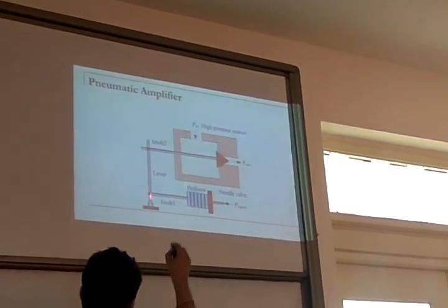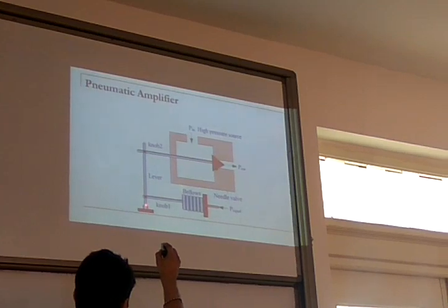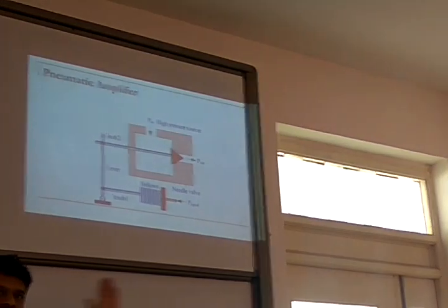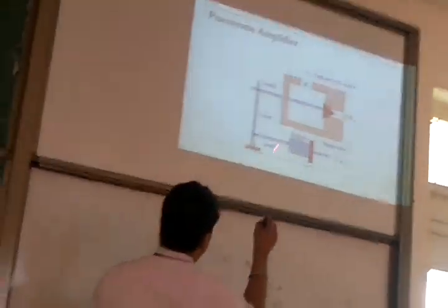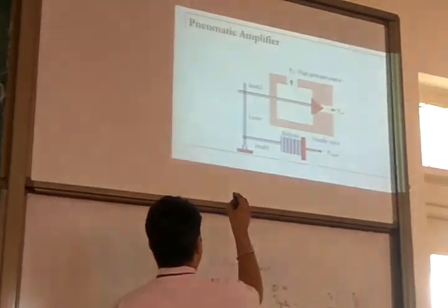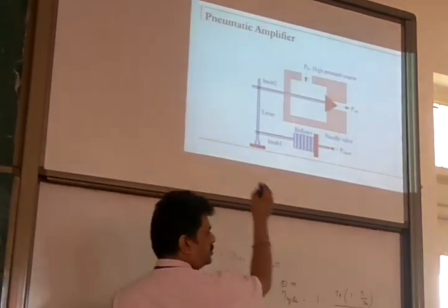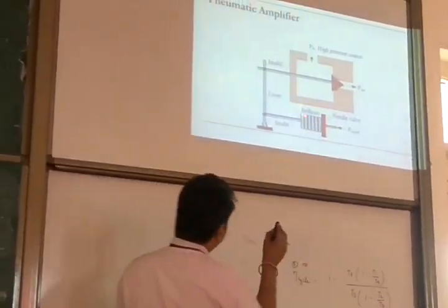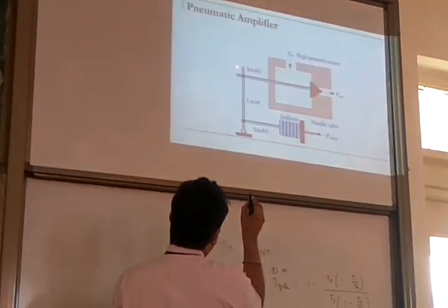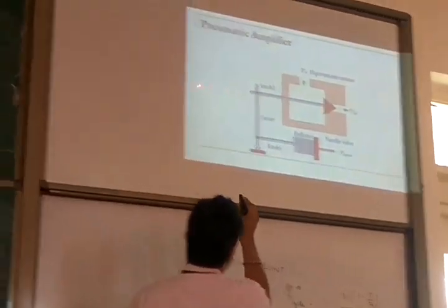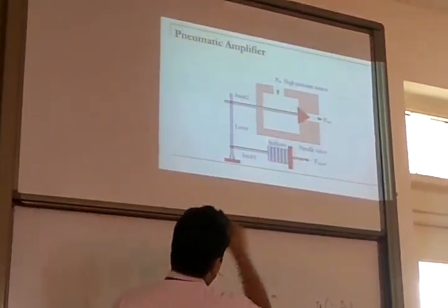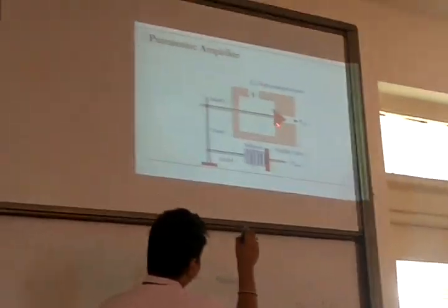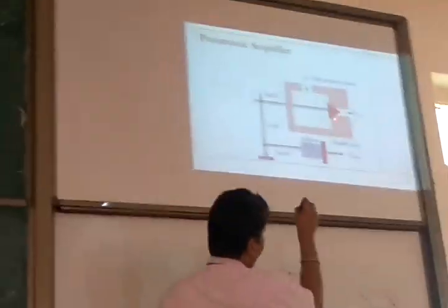The rod, this lever, the lever is hinged here. That means the rod can move like this, in the plane of the board. So the knob pushes the lever towards left. So knob 2 is also pushed towards left to a greater extent. This pushes a little, but that results in large angular displacement here. That pulls the valve spool to a greater extent. That results in opening of this valve.